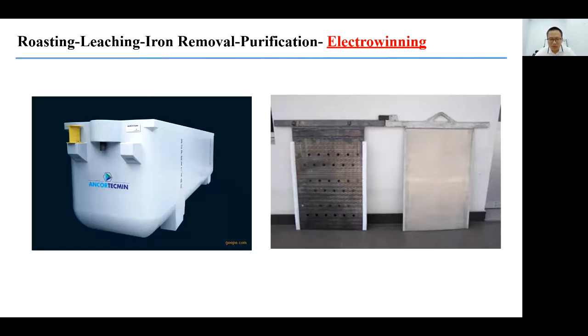Aluminum is a very good one here because it can resist the corrosion from the electrolyte, especially when we have some 200 gram per liter sulfuric acid. The aluminum oxide layer is very dense. It can transfer the electrons, but it can resist the corrosion.